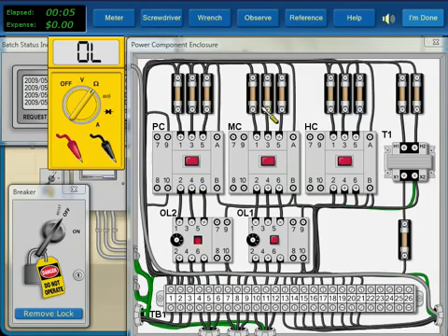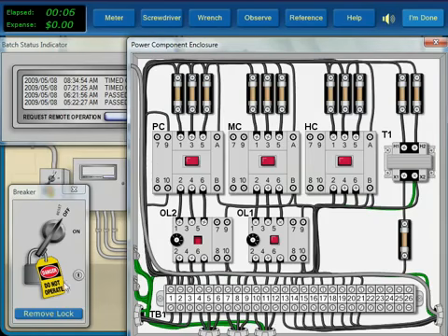To verify the repairs, we test the full path through the motor. The low resistance reading indicates the path is complete. Next, we get ready to operate the system to make sure there are no other problems.